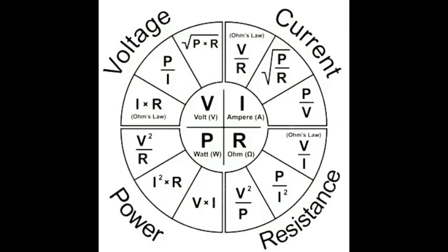If I'm going to be connecting a load to it, that load cannot exceed the amperage of that wire. If I'm connecting 2 loads to it, or 3 loads, and they're connected in parallel, what's going to happen to the amperage? It adds up, right? So we have to remember the rules for our parallel circuits: our amperage adds up and our voltage is constant, so that we can have a balanced circuit, because if not, our wires are going to overheat. So this is something that we always have to take into consideration.